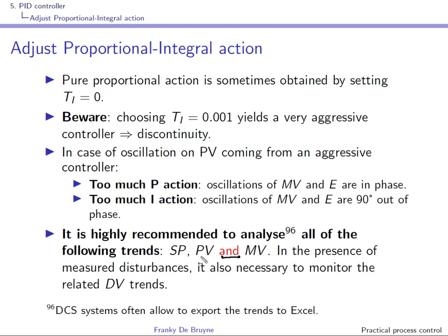Remember this equilibrium between the proportional kick and this I ramping when tuning a PI controller for processes with delay. Also, you have to look at MV to see the saturation effects that might be present.